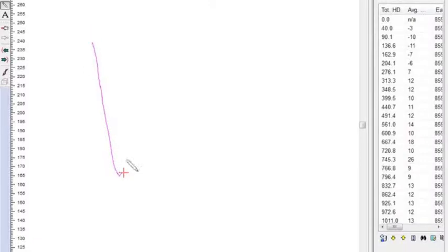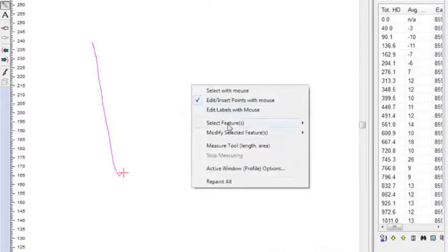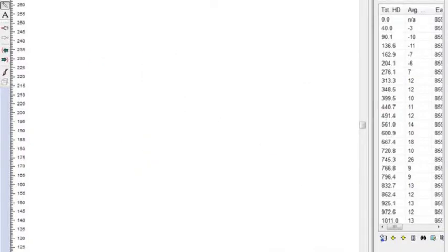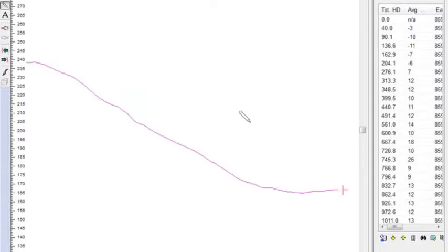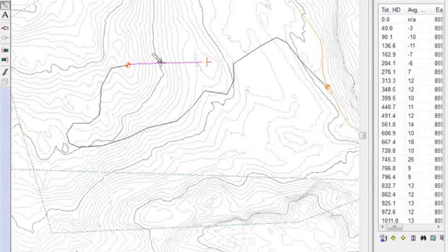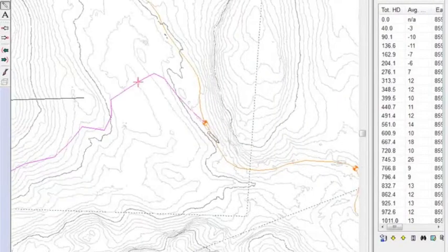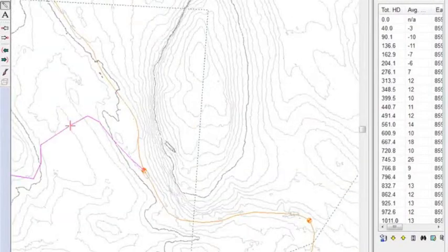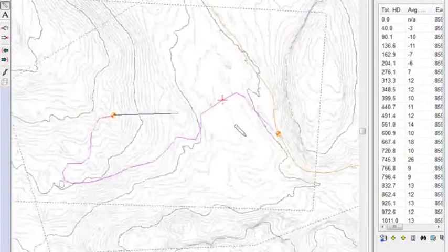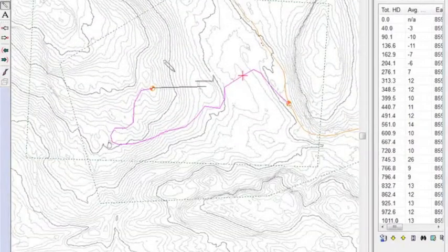And again, we are looking at a 10-to-1 distortion. So maybe for D-lines, you want to turn that back to not 10-to-1. There it is, undistorted. So there's a lot of planning you can do inside the terrain module. Back to the plan window. There's my little D-line. Here's my road. I do actually want to do another road along here. We'll do that later. Now let's design this road.